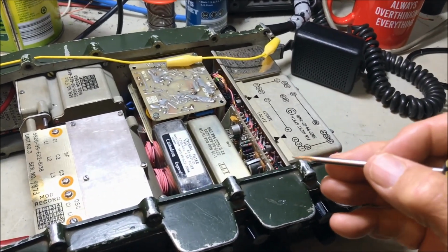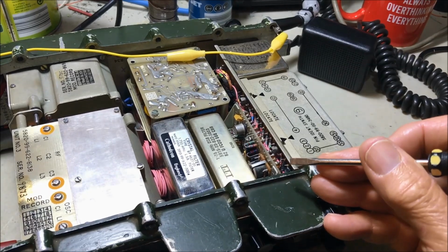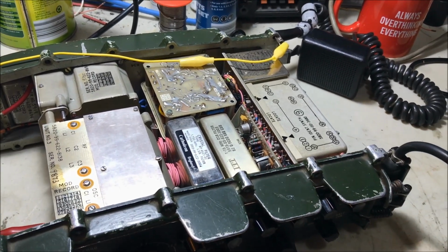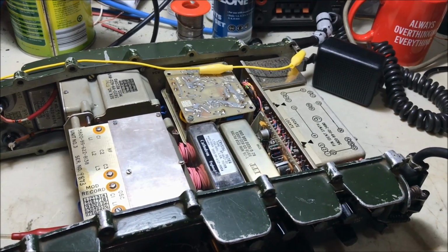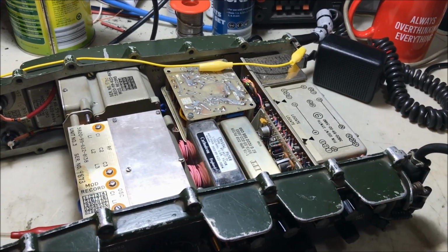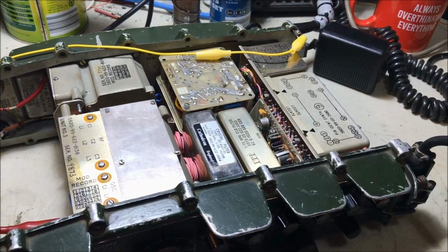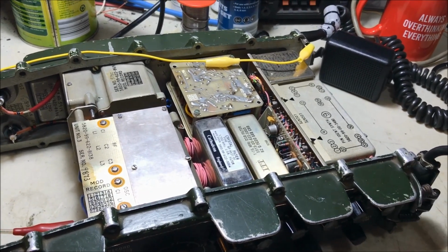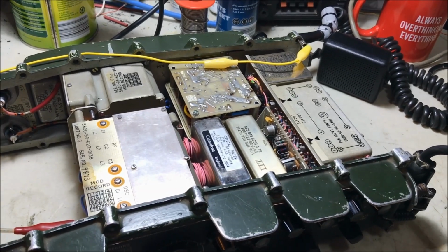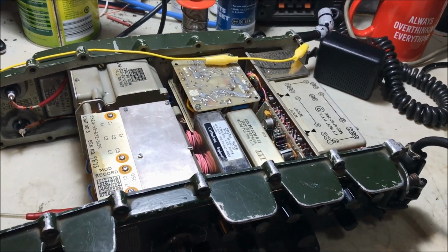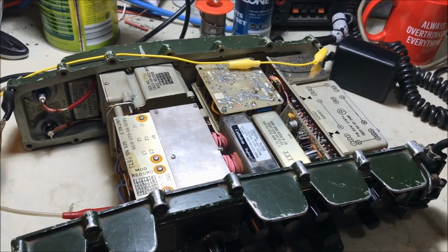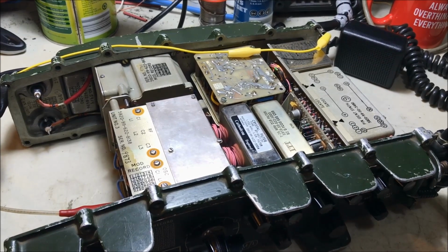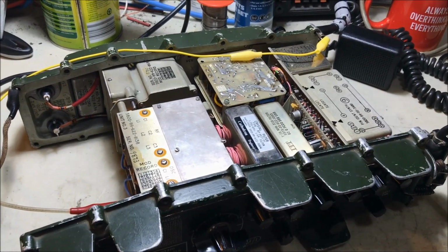Why didn't it have a 3-volt power supply? Because someone had jammed something down behind the synthesizer here, shorted the 3-volt pin to ground, and actually bent it. It was still touching the ground, and blew up the 3-volt supply. So I fixed the power supply, found out why it had blown: the pin was shorted to earth. I bent it back again and got that working. No audio. Went underneath, searched through and found a dry joint on the number 6 motherboard, and then we're up to the stage of the wobble.